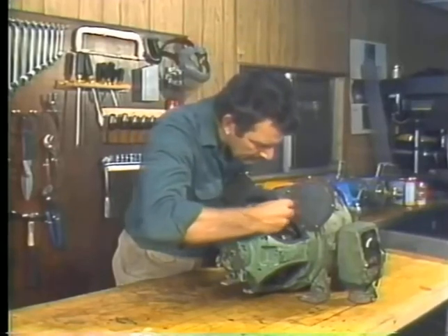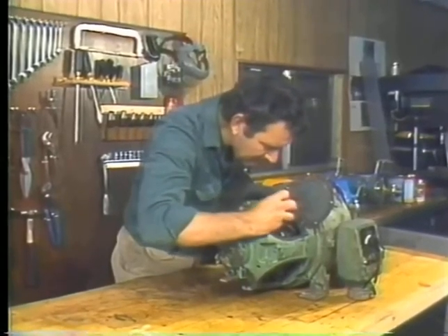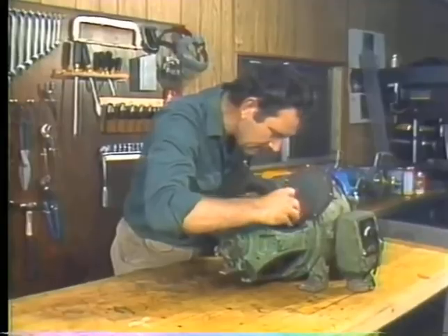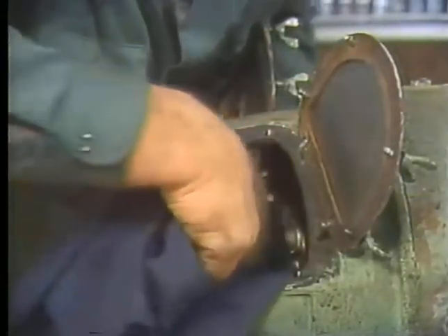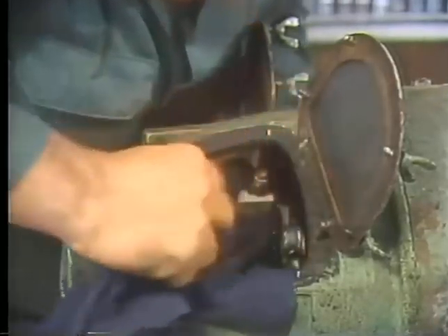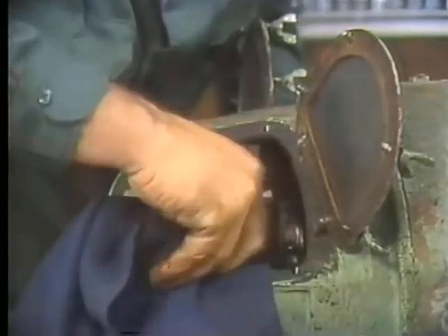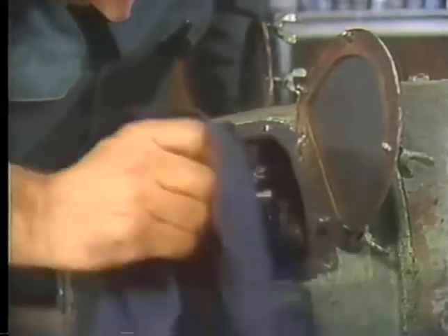if the motor's clean. In fact, cleaning the motor thoroughly is the first order of business in any maintenance procedure, and we'll start doing that now. Then we'll inspect each part as we go along for the problems we just mentioned. Open the inspection covers and vacuum the interior of the motor as thoroughly as you can. Then take an approved cleaning solvent and some clean rags and wipe out the interior. Be sure you observe the safety precautions established in your plant for using cleaning solvents.